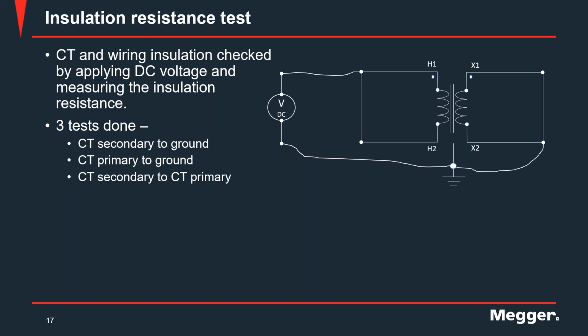Another way to generate flux in a CT is by applying DC current and maintaining that DC current for a period of time. So instead of changing voltage, you are increasing the time of the applied voltage and of the induced current that you are putting there, and then calculating the integral of that DC curve gives you the same amount of flux.